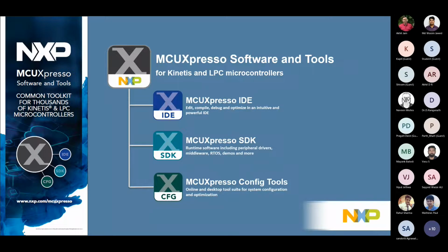For that, again, you can write software, or NXP provides a configuration tool with a pictorial representation where you can select each pin and define what peripheral function each pin should have, whether it's an ADC, PWM, GPIO, fault or whatever it is.